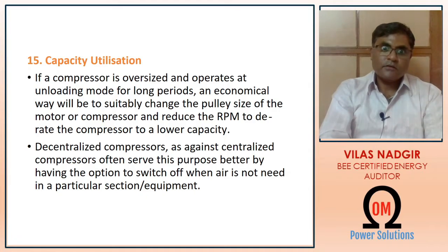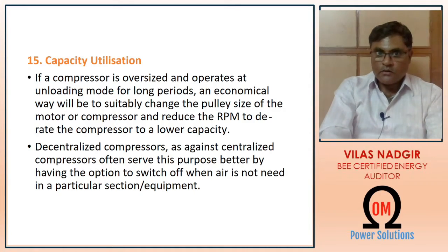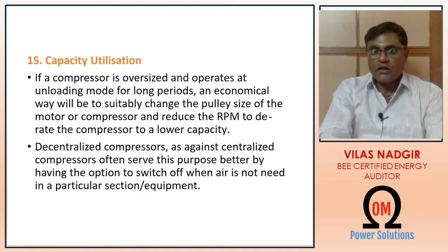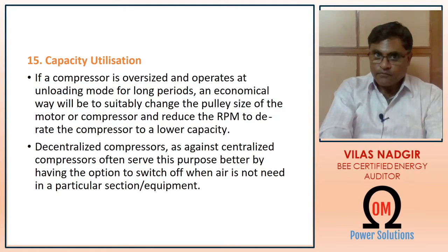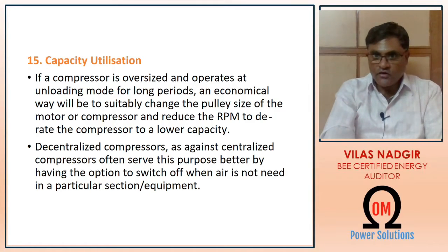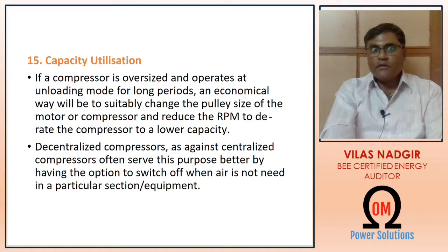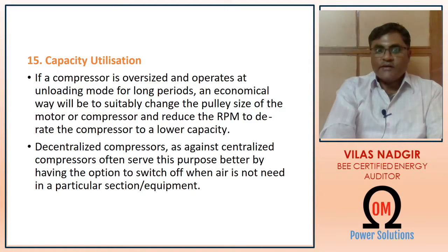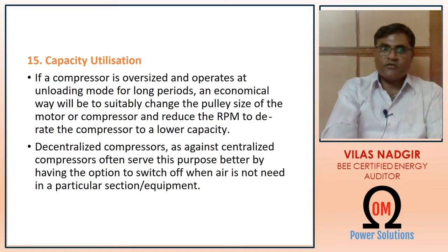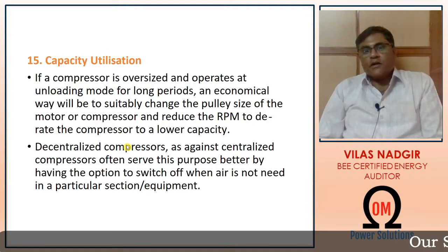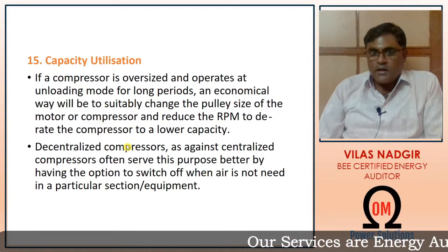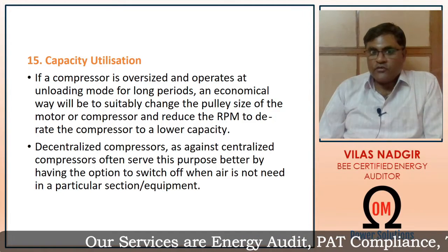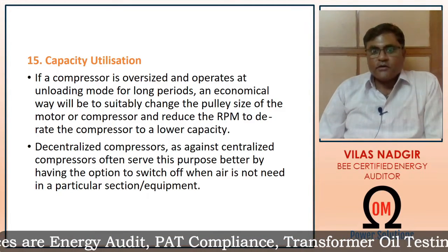I have seen that in many industries compressors are oversized, which means that usually for small requirements they are using very big compressors, and only for a small time period they use full capacity. This is actually not recommended because during underloaded condition the compressor usually draws very high power, and because